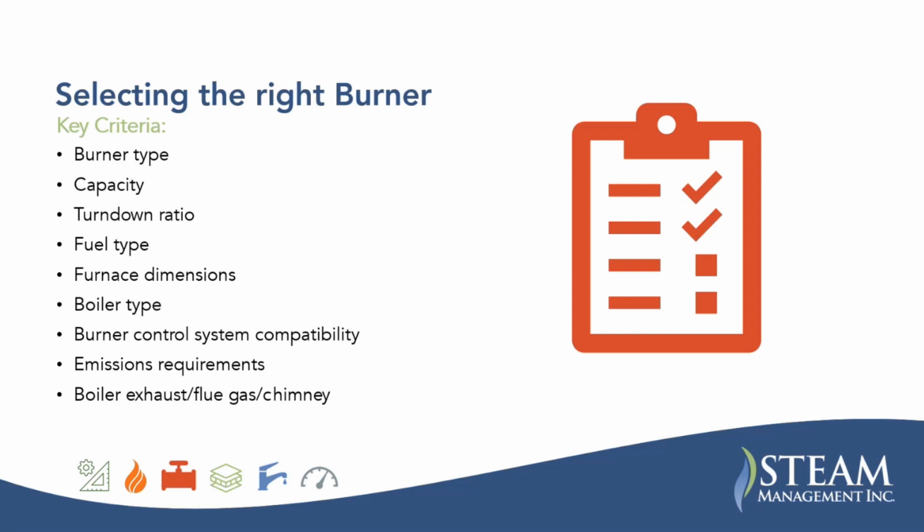Anyway, other criteria: fuel type. You have natural gas, fuel oil, biogas, etc. The burner manufacturer is certainly going to want to know that. They will also want to know the available fuel pressure. That matters for sure.